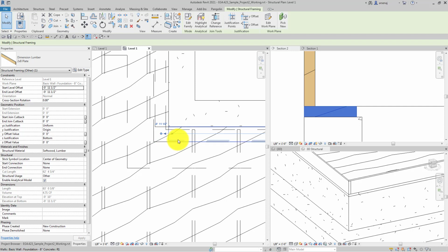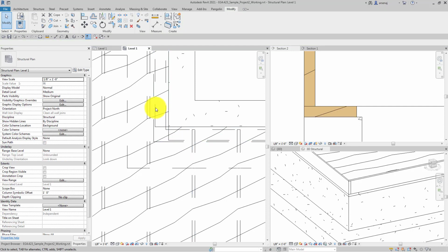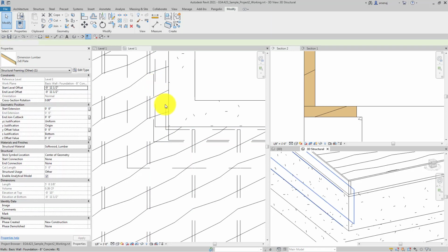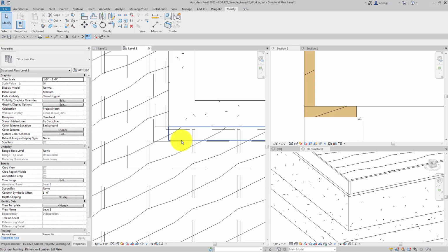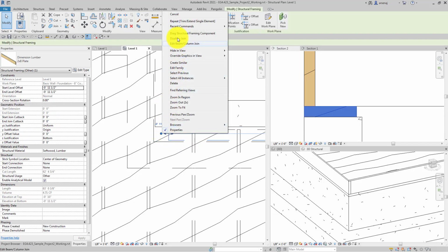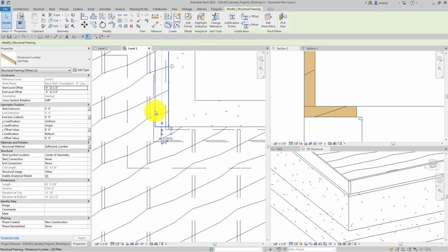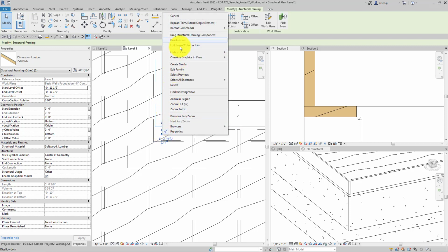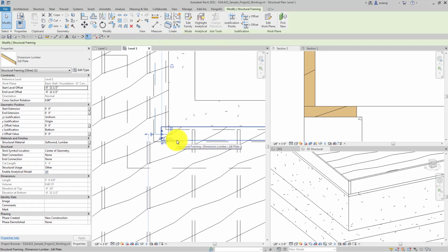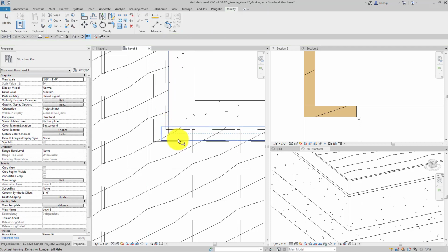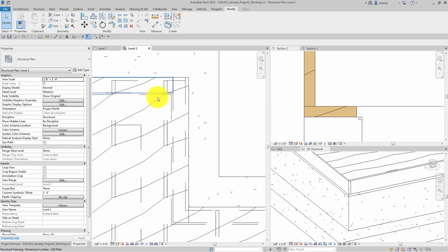And let me know if you have issues and can't get these to join or anything, because often you wouldn't want to quit at this point, because you want all of these to be accurate, so that you can see that yes, this top plate in the field, they would extend it so that it kind of rounds out this corner. So you might not know that you can disallow the join, and often there might be a reason, something that we could change to allow this join to happen, that I don't know off the top of my head, especially since the others are working just fine.